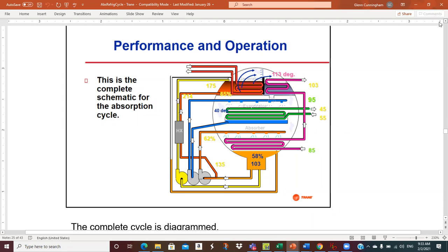And it's about 10 times that up in the generator, I think 1.35, 1.4, something like that. So it's roughly 10 times higher, but even 1.3, 1.4 PSI is a significant vacuum. So the whole machine's under vacuum. As we'll see, one of the issues is air leaking in.